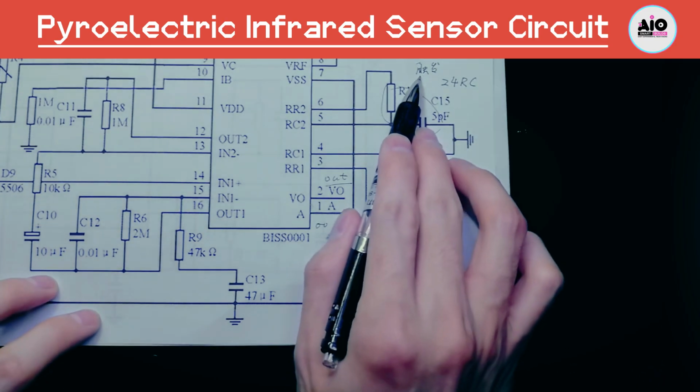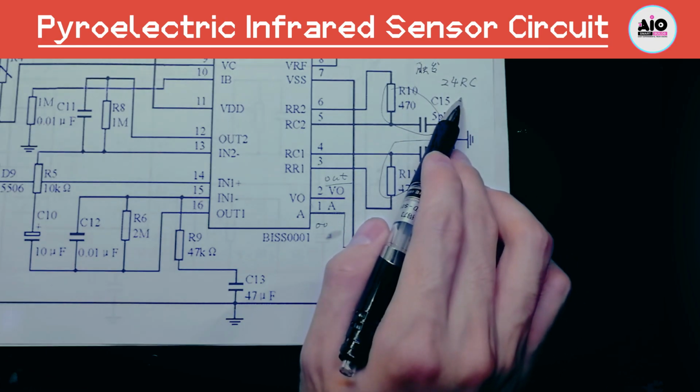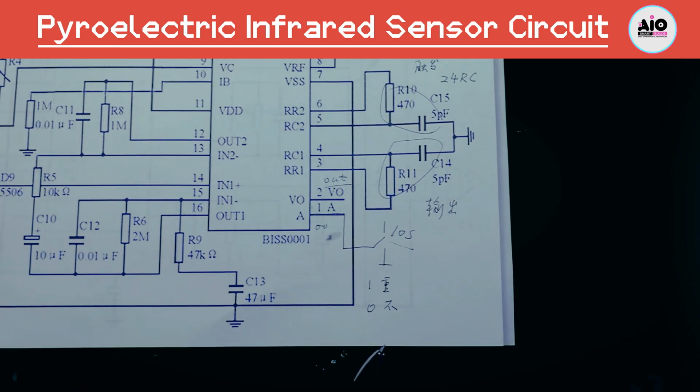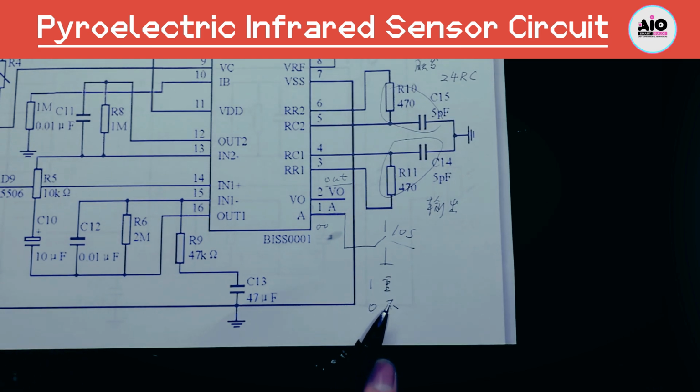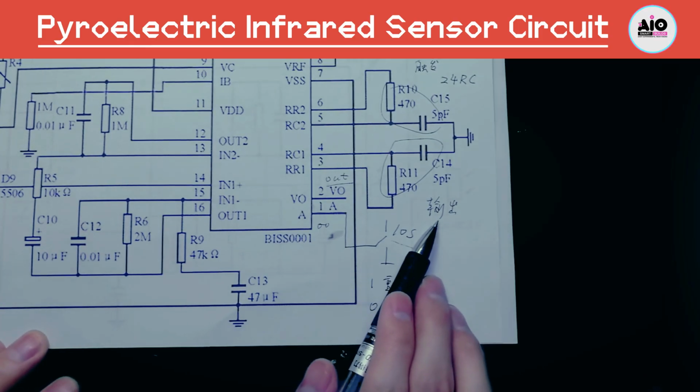That is, when the human body moves in front of the sensor, it reaches the output delay time and then immediately becomes low level, and then enters the trigger blockade. After the blockade delay, it will detect again, that is, there will be a logical change between repeated triggering and non-repeated triggering, the change of low level and high level.